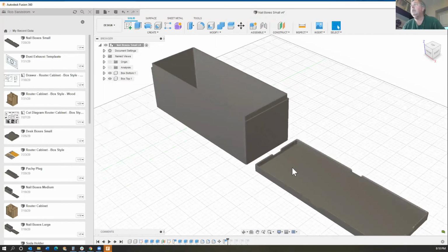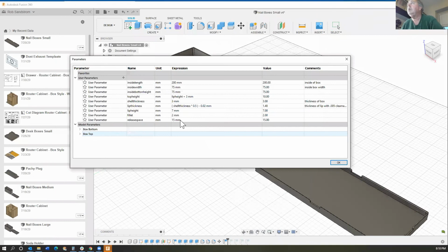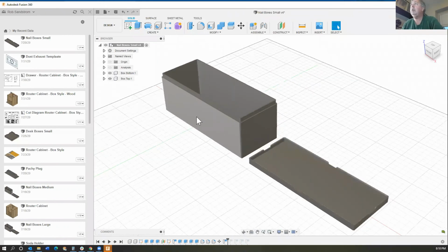And then I put these little notches in it, let me hold this up, so that I could easily pull them off the top, because they were kind of hard to get off. And at first they were sticking together, so by simply changing, once you got it dialed in, these shell thicknesses and lip thicknesses and stuff, you could get the right clearances so that it would come on and off easier or harder, depending on how stiff you wanted it to be or how well your printer was calibrated.